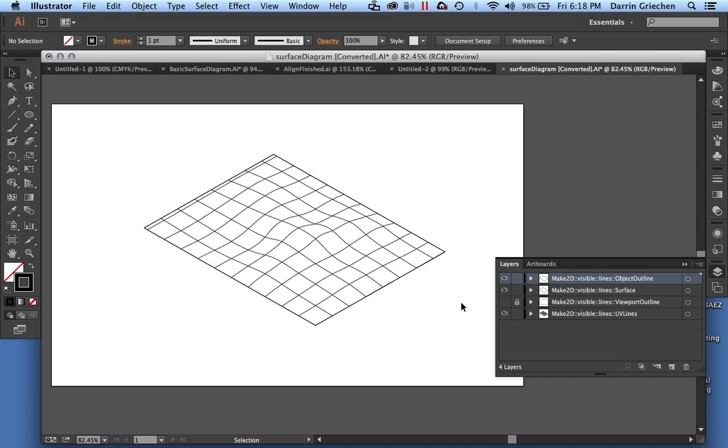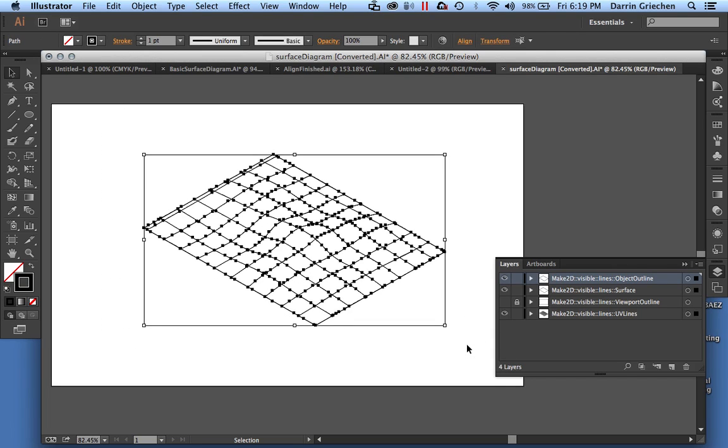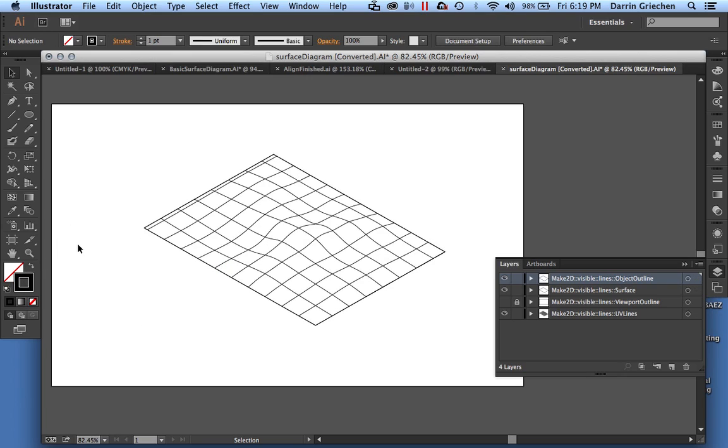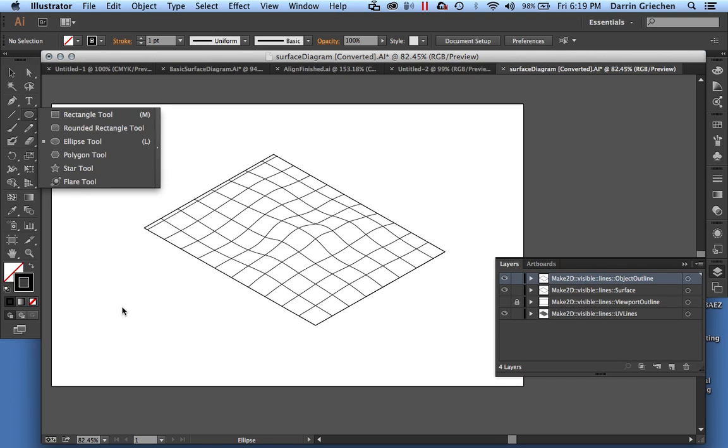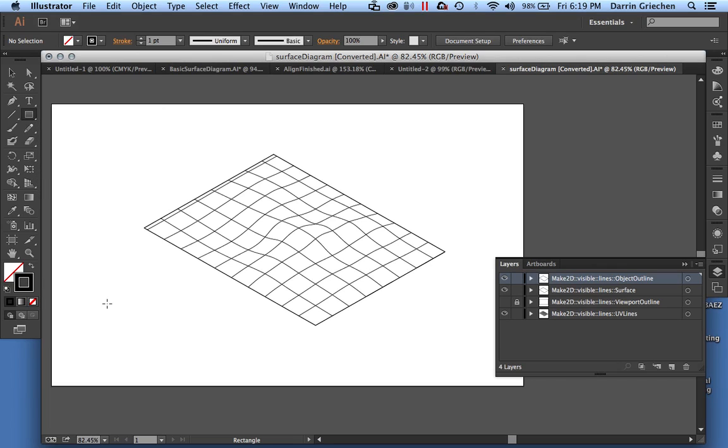Okay? So what we want to do is, just like in Rhino, if we left click and drag, I can select all of the artwork. Okay? And then I can come over here, and on this palette, this is how we start to tell what the appearance of these objects are. The stroke is going to be the outline, okay? And the fill is what's going to be filled on the inside. Just to show you an example, I will draw an ellipse, or maybe a rectangle.